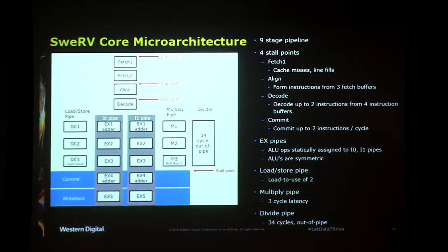And it turns out, from the experiences of companies like Freescale and Intel, this gives you an additional 20 to 25% boost. So overall, this kind of design, when renormalized to frequency, can beat the classical pipeline by about 45 to 50%. And I'll show you the Coremark data that proves that. On top of that, it can synthesize and run at a higher frequency because it has a deeper pipeline. So it has some frequency advantage.